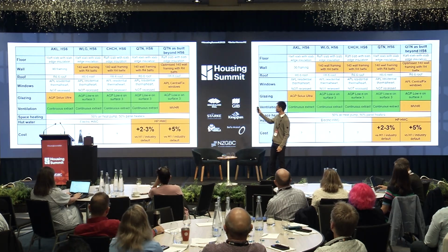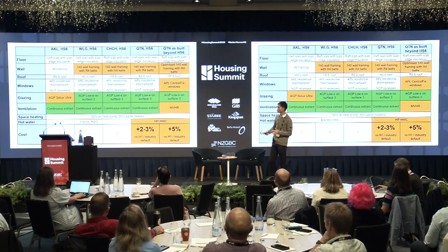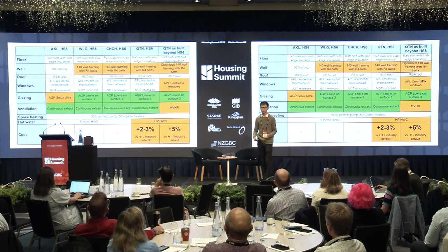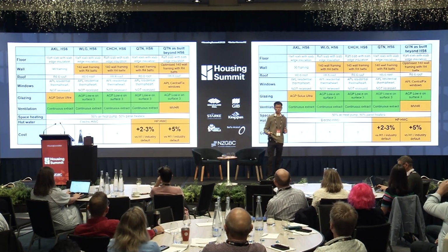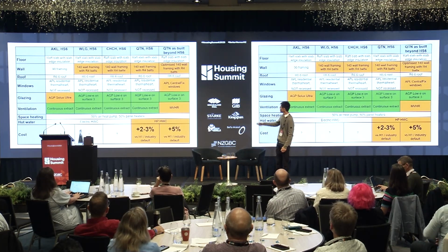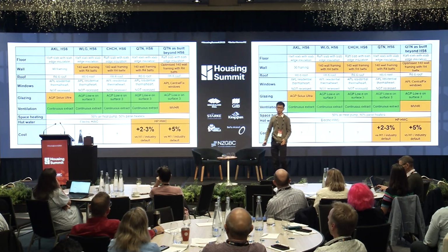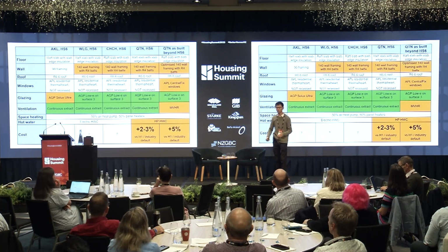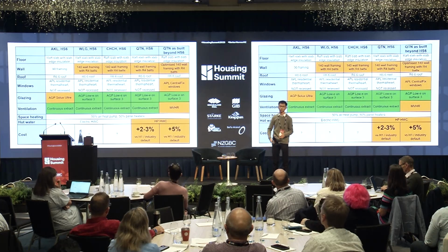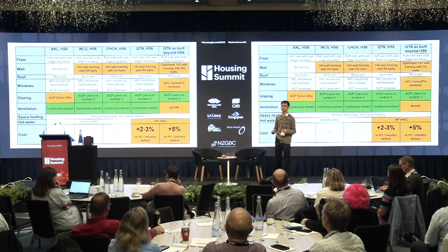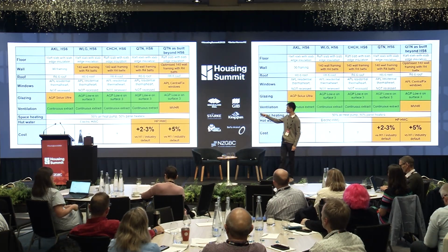Any item that's highlighted in orange are the actual upgrades we pay additional for to achieve a better outcome, and the green items are either completely cost neutral or can be done cost neutrally if we do that correctly. So our SBL version, we did go for the 140 framing, we trialed the APL central fixed window, we pay for NVHR because according to our own study in-house back in 2018, we figured out that's the only way to ensure a healthy, drier, better homes for our people.